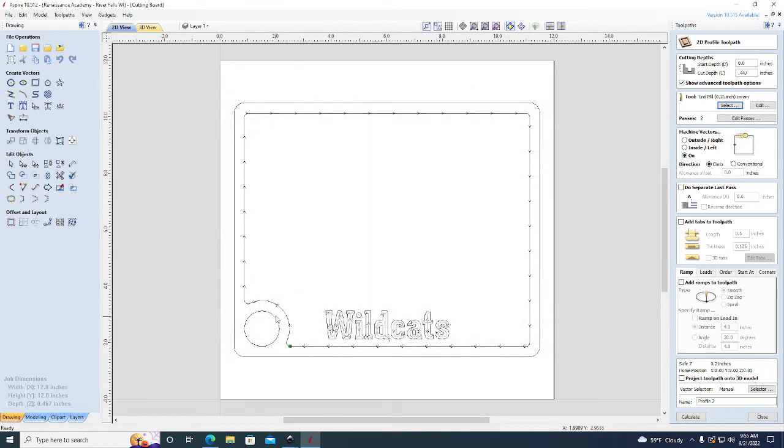For this next toolpath, we're going to be doing our circle right here because we want to cut out this hole. So for that one, we want to go on the inside. And when we cut this, we want to have a climb direction. So for our initial cut with our CNC routers, climbing is going to be a little bit easier on our machines and our router bits. However, it makes a better cut using a conventional toolpath. So what we're going to do is a roughing toolpath using a climb. So it's going to climb around.